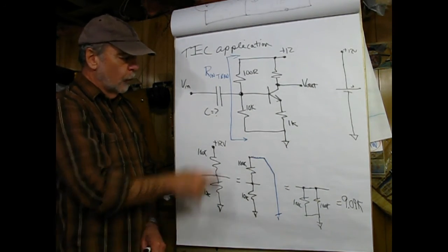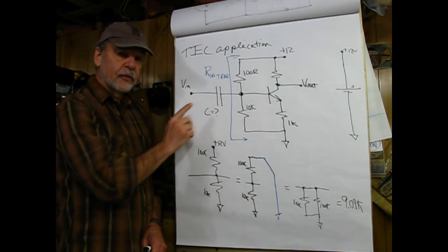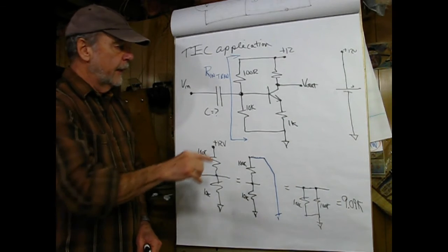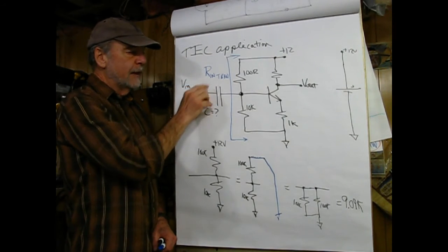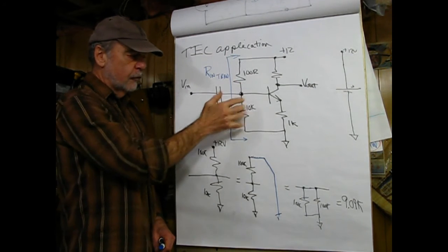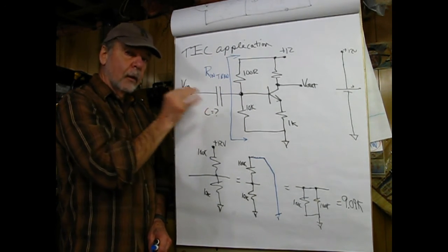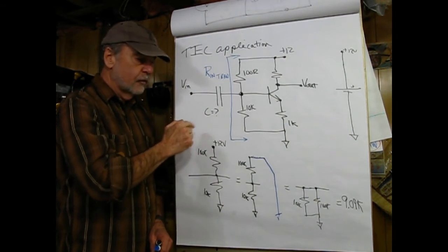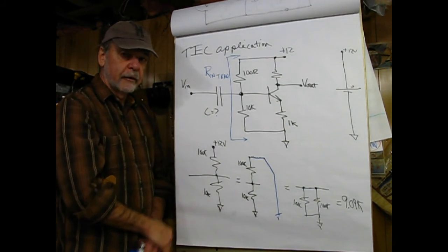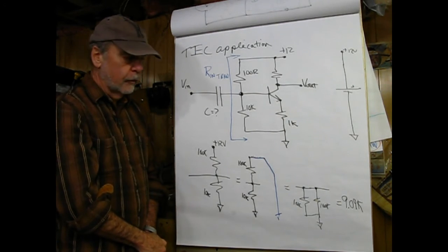So what I want to do is size this resistor, size the capacitor, but before I can do that, I have to know the Rin of the transistor circuit. And then whatever that resistance is, I make the opposition to current flow here 1/10 or less. And if I don't do this correctly, the base frequencies will be missing from the audio, and not a good thing.